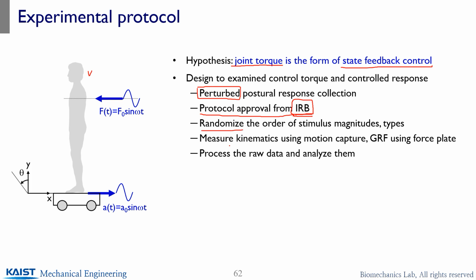And generally the measurements are kinematics and kinetics. Kinematics using the motion capture system, and kinetics using the ground reaction force plate. And that information could be used to calculate the joint torques and joint forces through inverse dynamics, what we have learned in chapter 1.